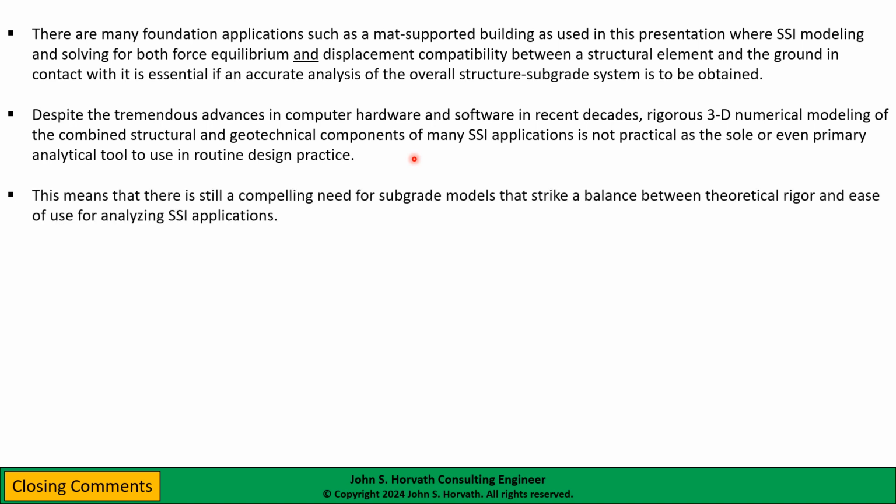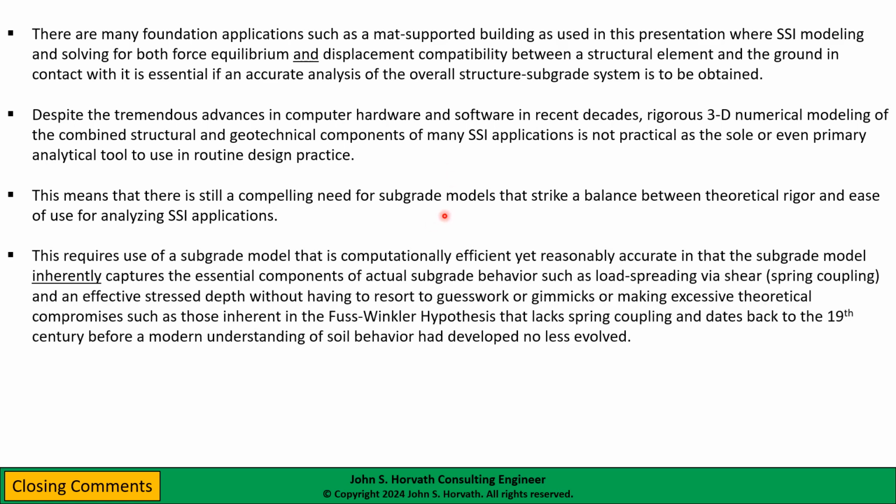So that's where subgrade modeling has come in. The point I'm getting at here is, even with the current capabilities of three-dimensional finite element software, there still is a need for subgrade models in practice that strike a balance between theoretical rigor and ease of use for analyzing soil structure interaction applications. So this requires a subgrade model that is computationally efficient, yet reasonably accurate.